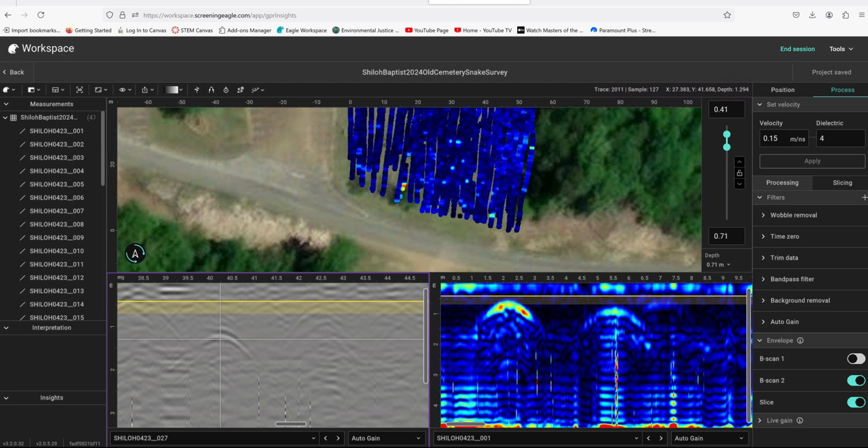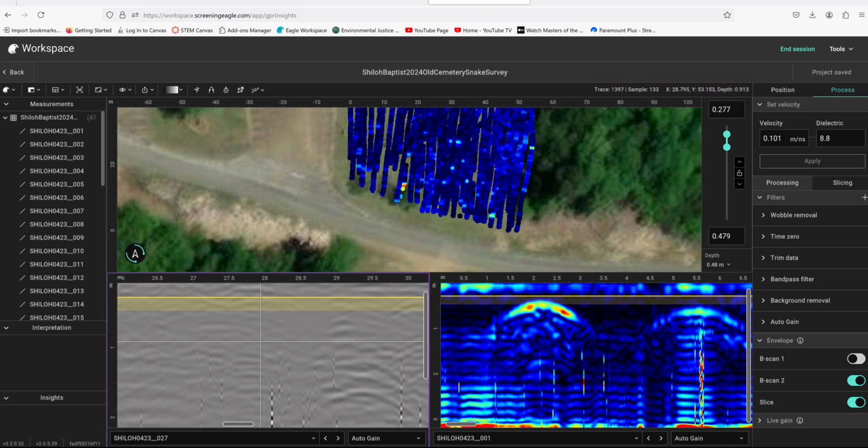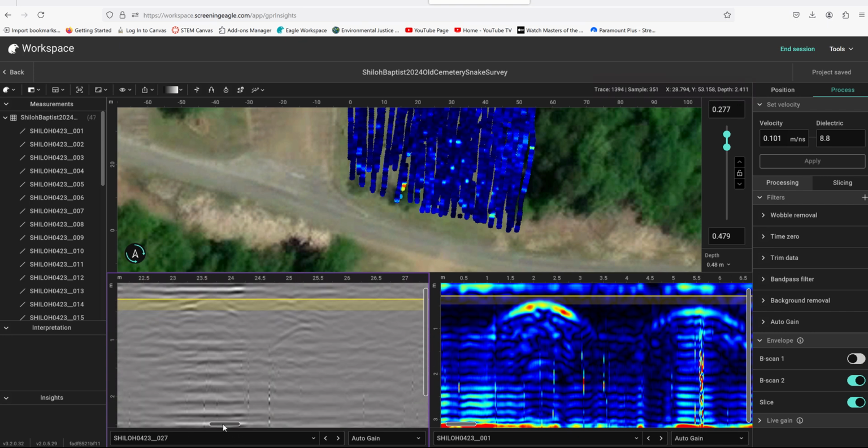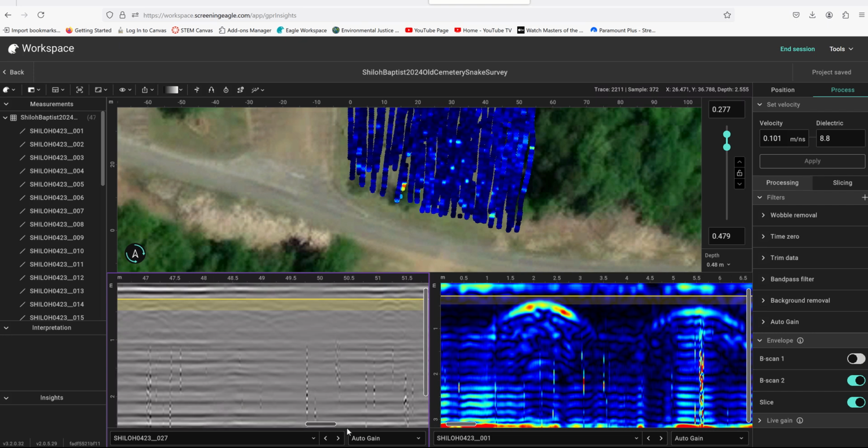And so here's a good example of a burial that is going to be a medium confidence level. I can come in and check my dielectric again just to make sure that my impulse is coming in pretty good. So we're looking at the second solid signal there, and I'm going to pull these guys in here and see what the dielectric of that particular one is. So it looks like we're changing our speed value there, which is interesting, that we've got a soil type change. It's probably because it's really forced on one end and not on the other. We can run through, but we're still inside of our known areas here.